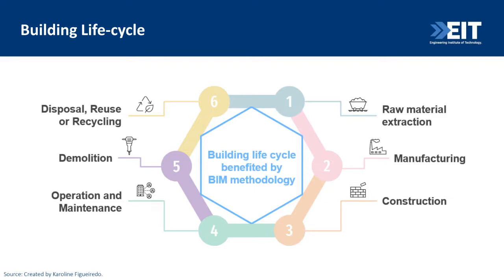It's possible to use BIM to improve the demolition stage of a building. So integrating BIM in demolition or in deconstruction is considered an effective pre-deconstruction audit to assess the recovery, reuse, and recycling potential of building components and materials. So if you put information about all the building components, the building equipment, you will have the information to analyze the better way to demolish your building, okay? So we can use the BIM methodology through the whole life cycle of the building.